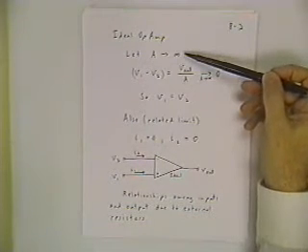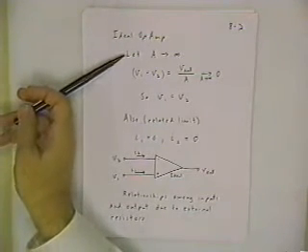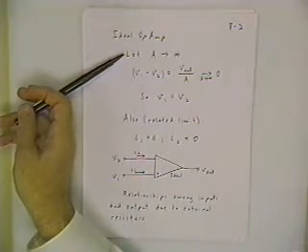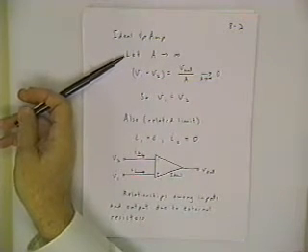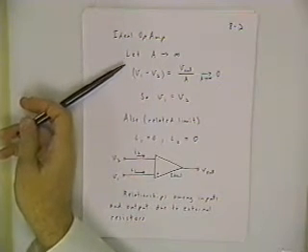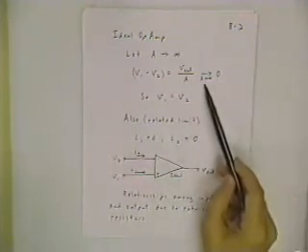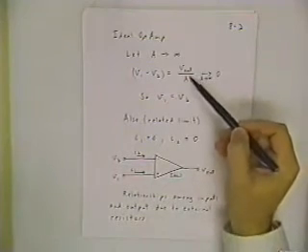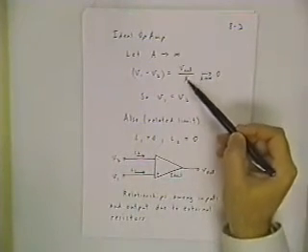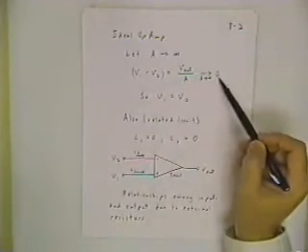What you need is a voltage gain of infinity, which obviously, if you think about that practically, is not achievable, but we can get very close to it with a well-designed integrated circuit package. So let's suppose for a moment that we can let the open loop gain go to infinity. See what our equation becomes from the previous slide. You just divide through by A on both sides and then let A go infinite, and that means that Vout over A, if Vout is a finite number and A goes infinite, that difference between the inputs goes to 0.